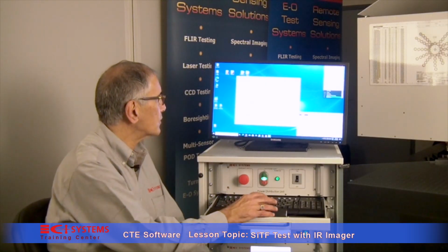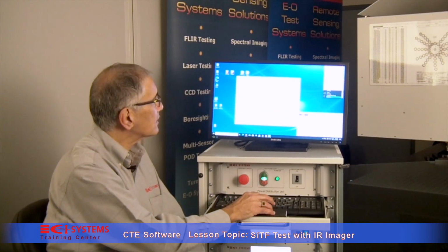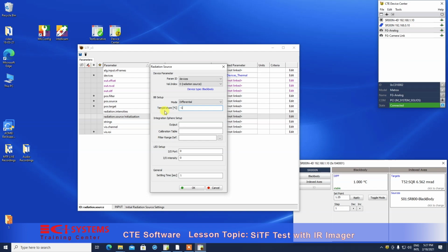This has more effect for setting up the region of interest. So we need some sort of initial temperature. It could also be -3.5 or whatever, as long as you have the flexibility of setting any temperature that you want, as long as there will be some sort of contrast between the background and the target display, then you'll be able to select the region of interest. This is the reason you need this initialized temperature.